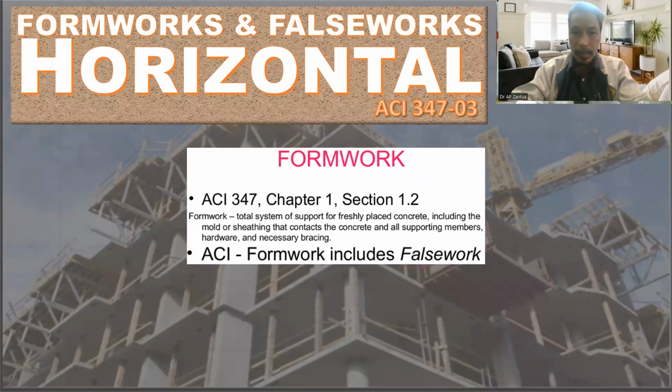So those are vertical. What about horizontal? We also have horizontal. Actually, there are more horizontal formworks than vertical formworks. So again, using the definition of ACI 347, formwork is a total system of support for freshly placed concrete, okay, including the mold or sheeting that contacts the concrete and all supporting members, hardware, and necessary bracing.